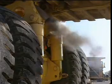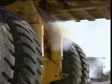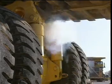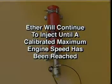With this feature, the ECM can inject ether into the intake manifold while cranking if the engine is below a calibrated minimum coolant temperature or intake manifold temperature. The ether will continue to inject until a calibrated maximum engine speed has been reached.